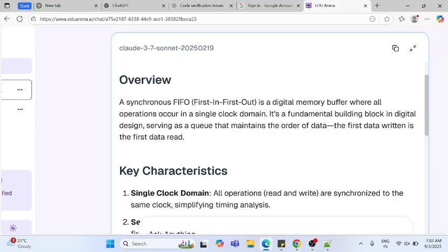When you pass the data from high frequency to low frequency, the high frequency block can transmit data at a higher rate, whereas the low frequency block has a very low sampling rate. Because of that, it can miss the data. Similarly, if you pass the data from the low frequency end to the high frequency end, the possibility of malformed data entry is more. To avoid that, FIFO is used as an interconnect structure to communicate the data effectively between two ends.